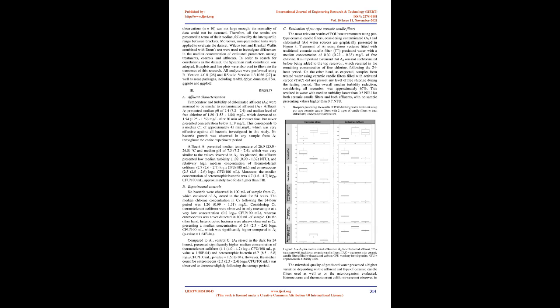All water samples were tested for turbidity, 2130, using a portable turbidimeter, Hach 2100P, Loveland, USA, pH, 4500 H+, with a pH meter, Digimed DM22, Brazil, and temperature, 2550, at the time of collection, except A2, which was analyzed only for pH and free chlorine, 4500 Cl G, using a free chlorine checker, Hanna HI 701, Smithfield, USA. Moreover, samples from A2 and C3 as well as from TT and TAC, treating chlorinated water source A2, were also tested for free chlorine.